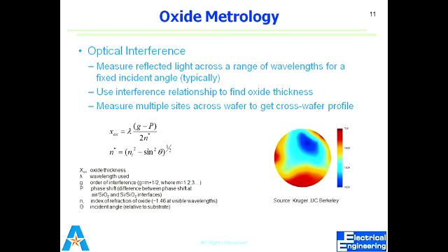So you should exactly know the index of refraction for your oxide layer, and then you can use this optical interference method to find the oxide thickness. As the formula shows, X oxide is given by lambda, that is the wavelength, G, that is the order of interference, and after that Ni, that is the index of refraction of oxide. Approximately it's 1.46 at the visible wavelength.